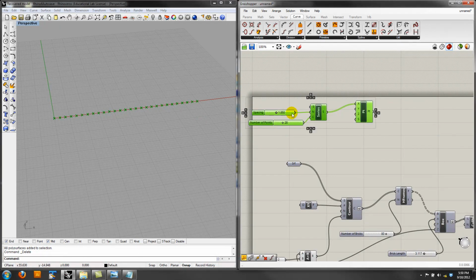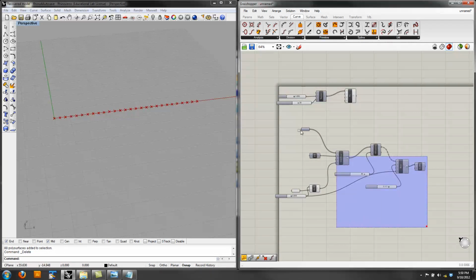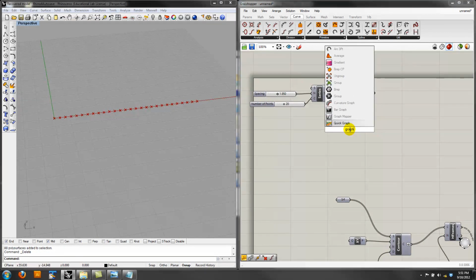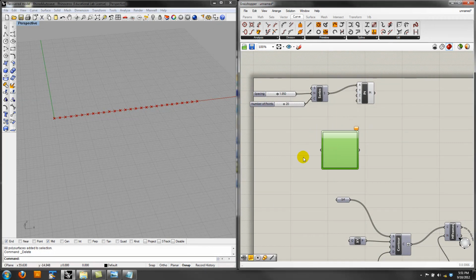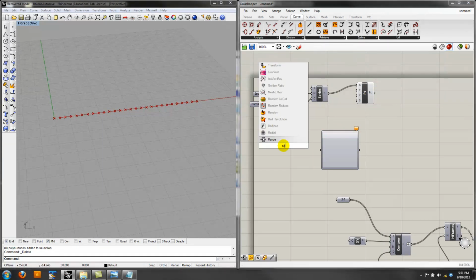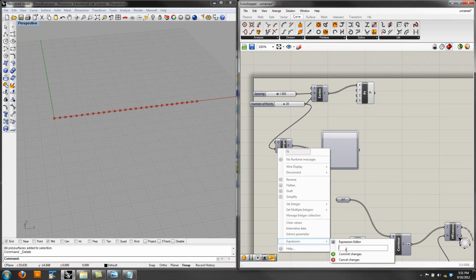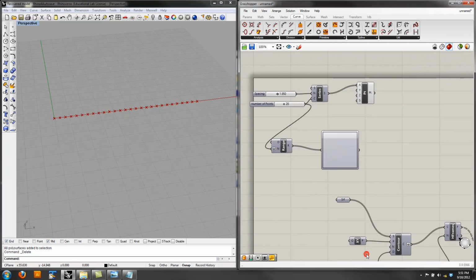Then the other bit that we did was to play with the y value. Remember the x value. And if we use a graph mapper to vary the y value, we get these interesting mathematical curves. And to do that, we put a range in, and the range is always one less than the other series that we put in, so n minus 1. You know, this is something that we've done so many times. This pattern should be ingrained in you. We have a series value and a range value that varies, and we plug these in for a point.